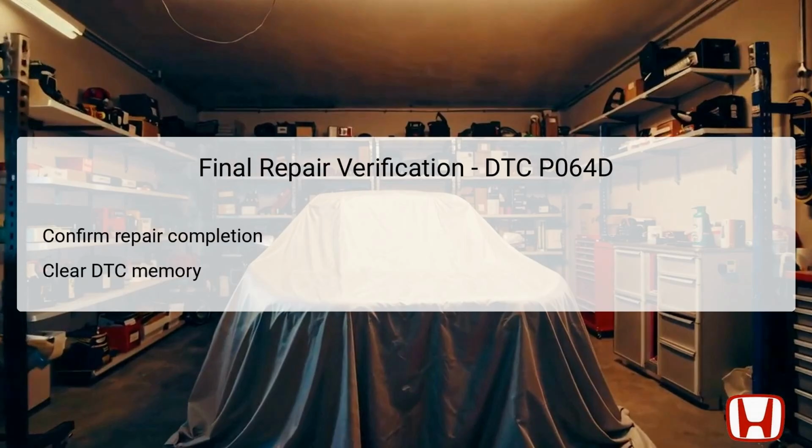Upon completing the necessary repairs related to DTC P064D, it is vital to verify that the repair has been effective. This involves confirming that all components are functioning correctly, specifically the AF sensor and the PCM. Once you are assured that everything is operational, the next step is to clear the DTC memory using a diagnostic scanner or through the vehicle's onboard system.